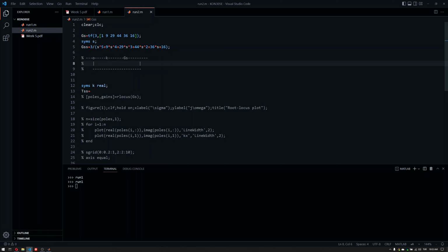And at ideal conditions, what we want to get is basically reference tracking. This is called reference tracking. If we apply a certain input value, the output value should eventually reach that value and follow it. So this is basically our aim here. And this root locus plot here helps us out in determining whether it is going to track or not, and how it is going to behave during the transients, because, well, transients are a thing. We have a dynamic system, we apply a certain change to the input, and it will have effects.